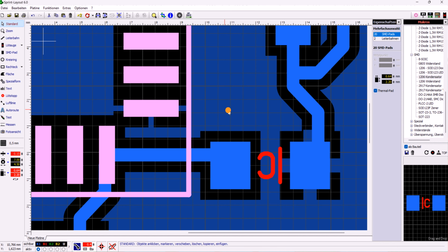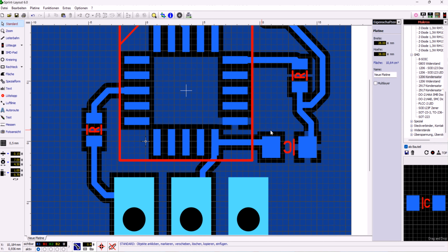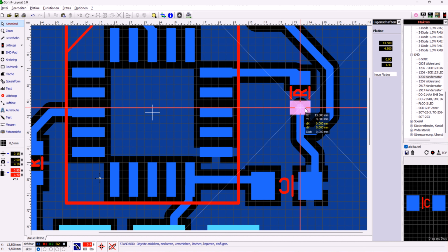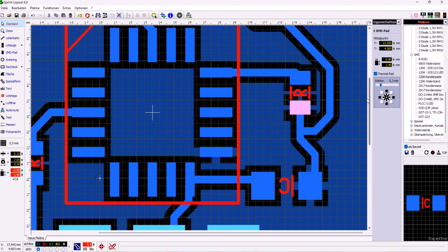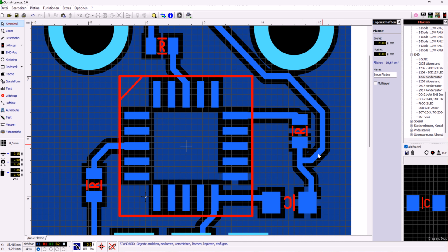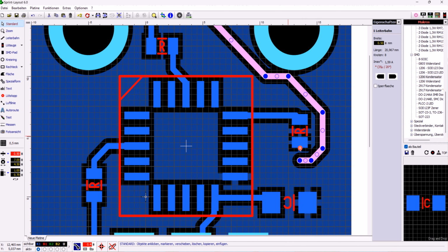Okay, so still we want to edit it. Press Alt and click. We want it a little wider, won't we? Yes, we want. So now also the Z pad. Press Alt, one click, thermal pad. Here maybe it doesn't make sense to go to 0.3 millimeters of clearance. Let's delete this trace, it's obsolete now, because that's connected to ground.